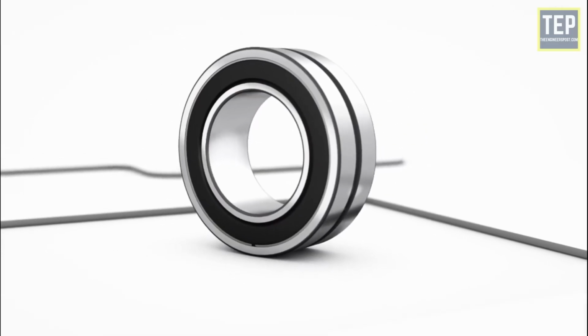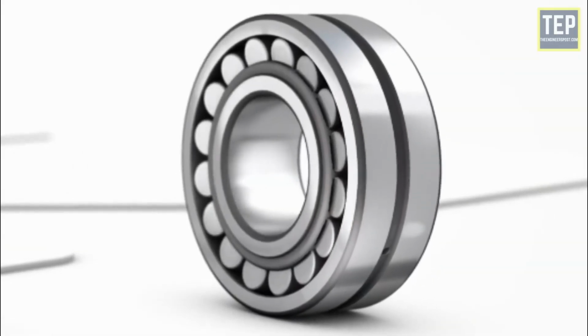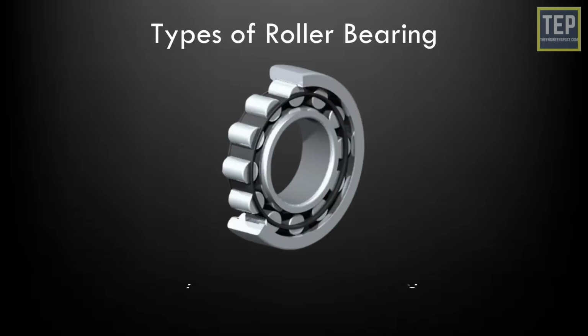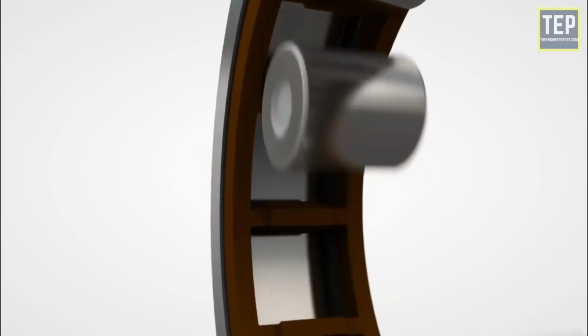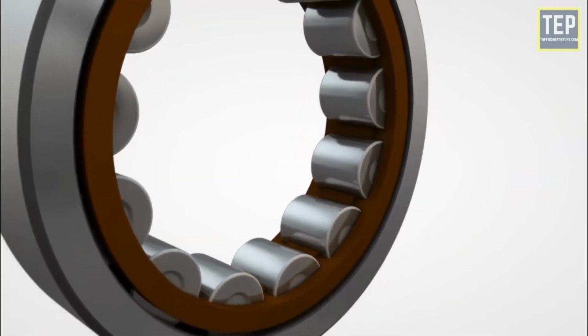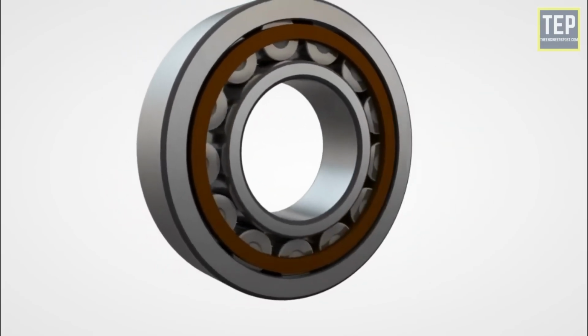Roller bearings contain cylindrical rolling elements instead of balls as load carrying elements between the races. In roller bearings, there are also various types, such as cylindrical roller bearings, which use line contact between the rolling elements and the raceways, optimizing the distribution of stress at the point of contact. Cylindrical roller bearings have a very high radial load rating. Depending on the design, they may also be able to transmit limited amounts of axial loads.